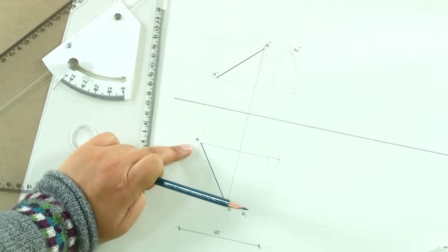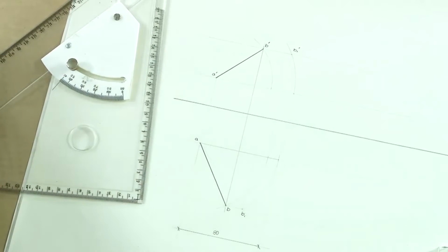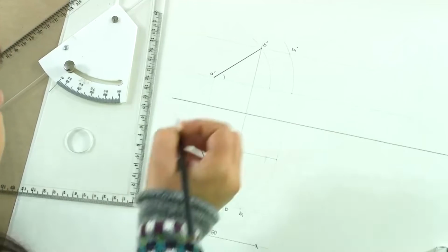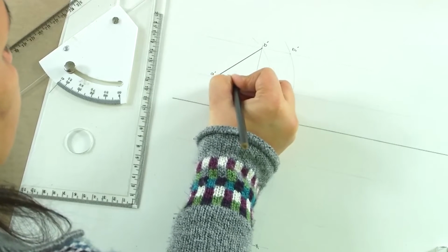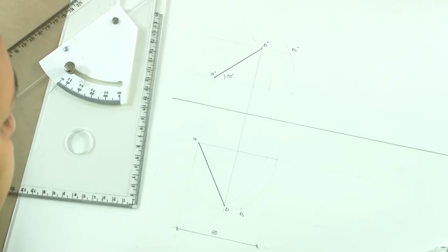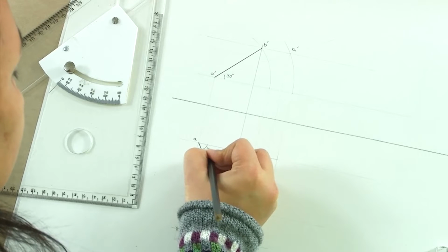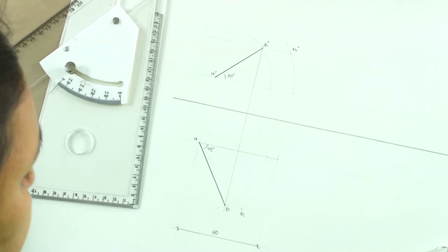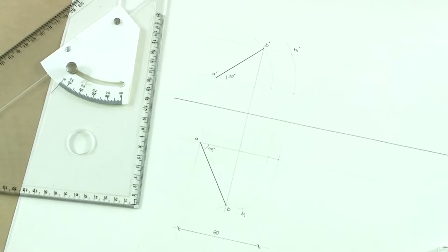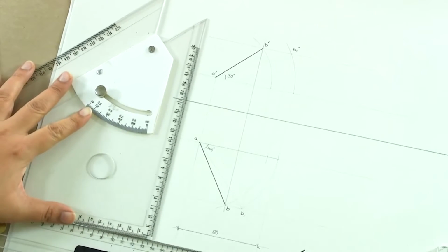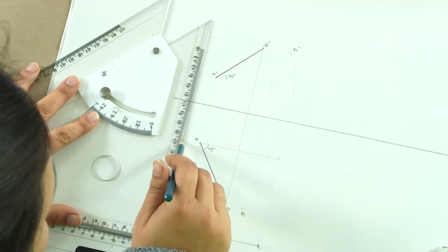The next thing is, it is making an angle of 30 degrees with HP. Now, we clearly know that this angle of 30 degree has to be shown in VP, assuming that this was parallel to VP. So, this is the angle 30 degree which it made with HP, and the angle that it makes with VP will be seen in the top view, which is 45 degree here. Also we have this 3 centimeter above HP and 4 centimeters in front of VP. So, we will make this.